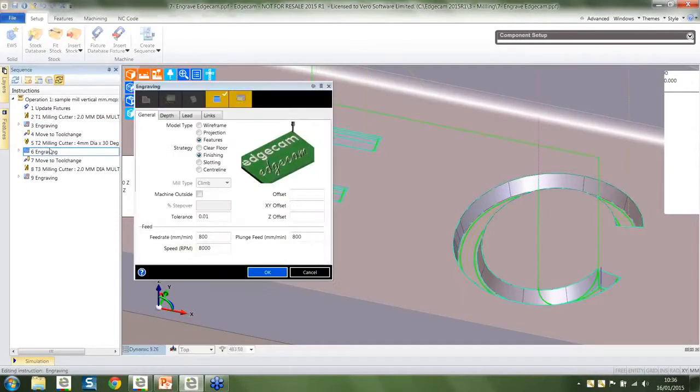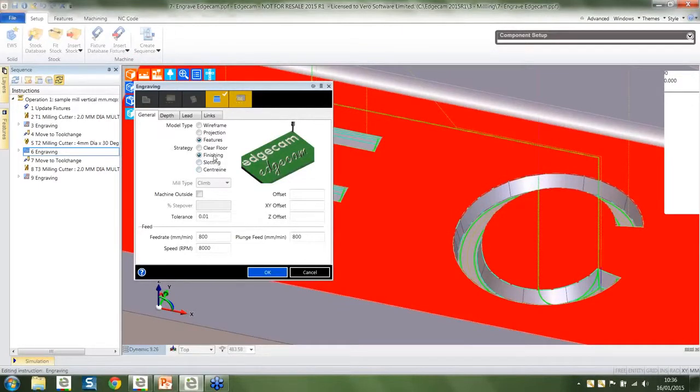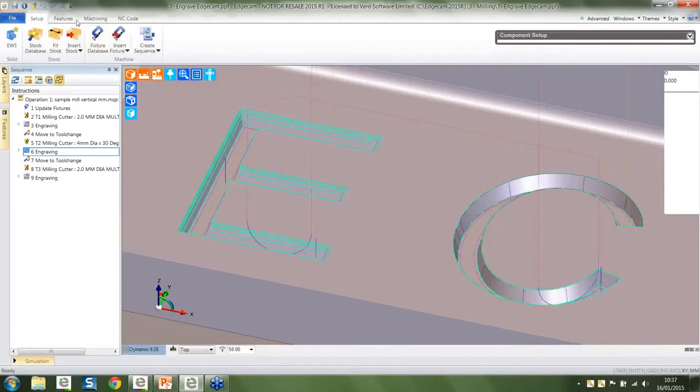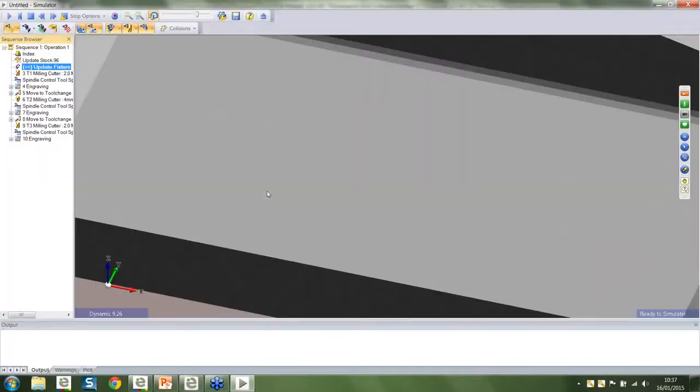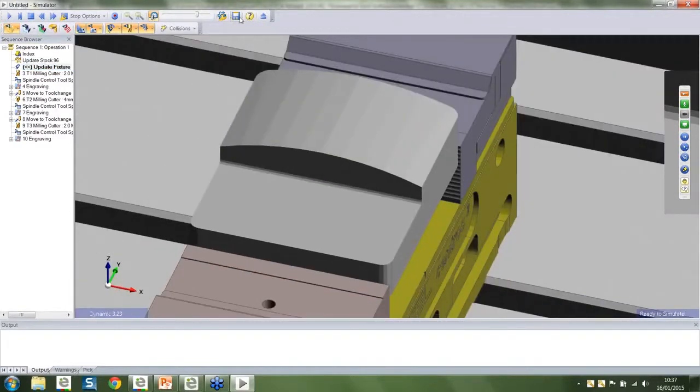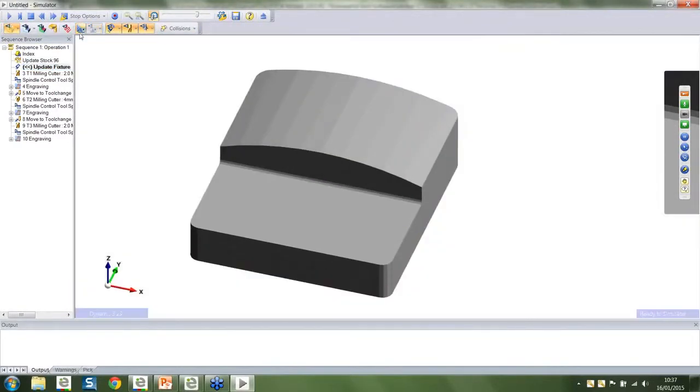The other item that we'll see in engraving is the finish, and this is very, very specialist. We tend to find that engravers will use a taper tool, and when the tool reaches a corner, internal or external corner, the tool ascends to the top and then descends, feeds down to the base, and it's actually forming the corner for us. Let's take that into the machine simulator. It's probably better off seen inside the machine simulator, and for purposes of this I'm just going to turn off the machine itself. So the first one is the slotting command.